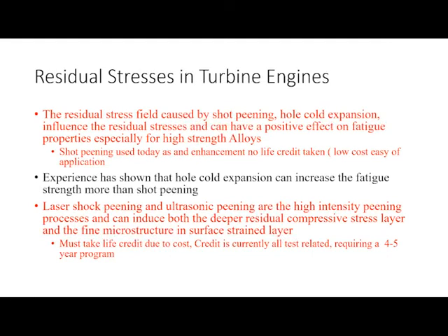And then when you get into residual stress, specifically from this mechanical side, there's kind of two areas I put these into. One is shot peening, or you could do hole cold expansion. They have positive effects.